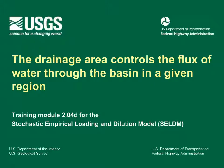This training module describes methods used to estimate drainage areas. The drainage area is important because it controls the flux of water through the basin in a given region. The precipitation and prestorm flows are multiplied by the drainage area of the highway site and the upstream basin to calculate storm flows. This is training module 2.04D for the Stochastic Empirical Loading and Dilution Model, SELDM.